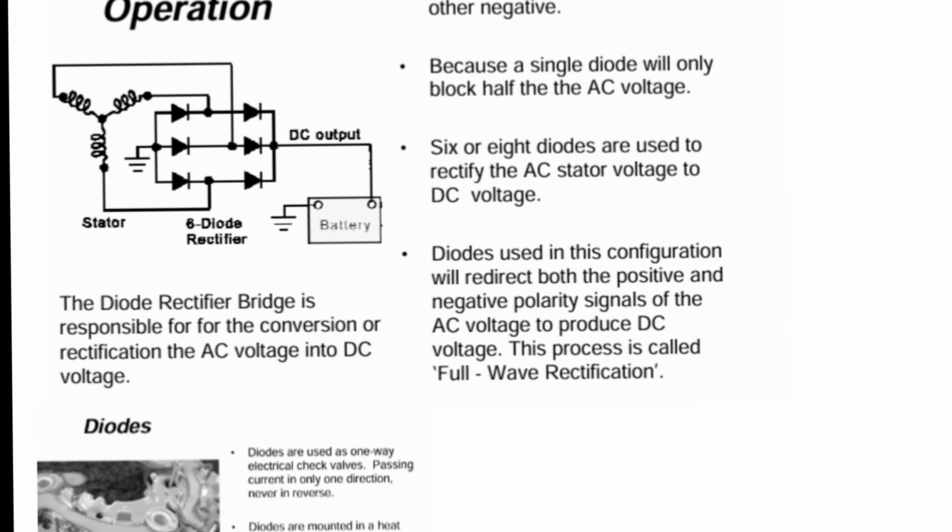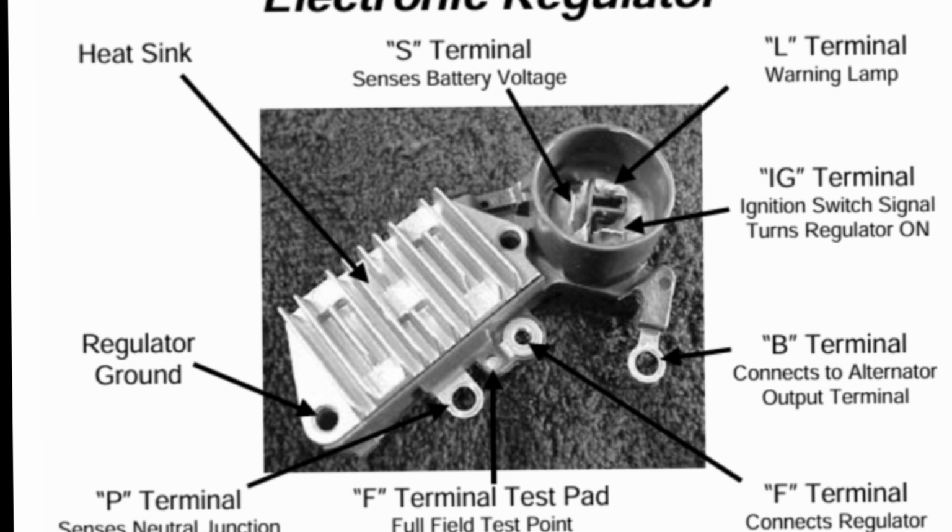Internal components explanation. Inside the alternator. Stator. Stator contains 3 windings. These windings generate 3-phase AC current. Rotor. Rotor rotates with the shaft and creates magnetic field. Windings. 2 types. Rotor field winding. Stator winding. Rectifier. Uses diodes to convert AC into DC. Regulator. Controls voltage output according to vehicle electrical load. Carbon brushes. Provide electrical contact to rotating slip rings.